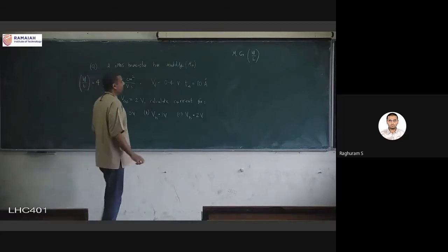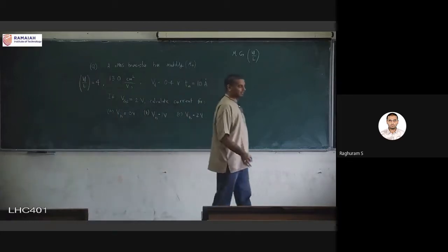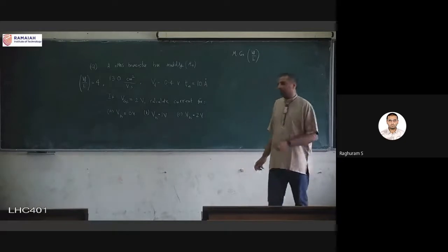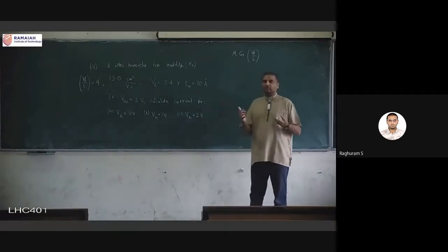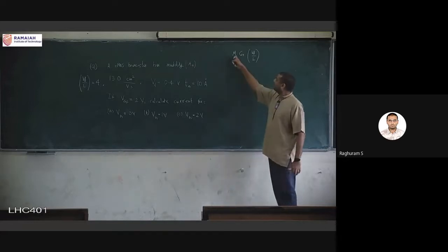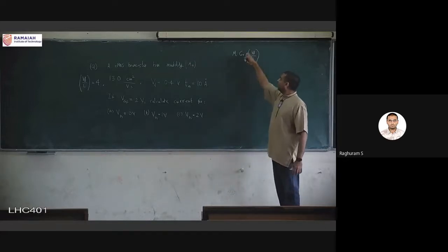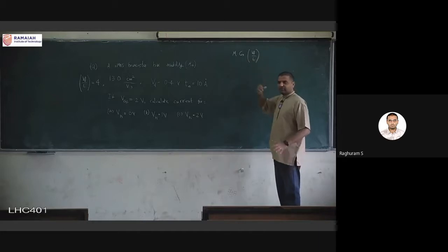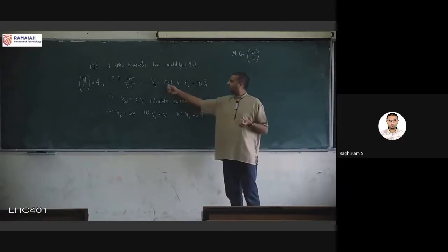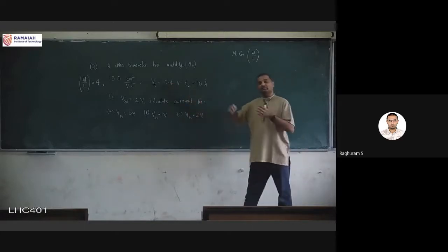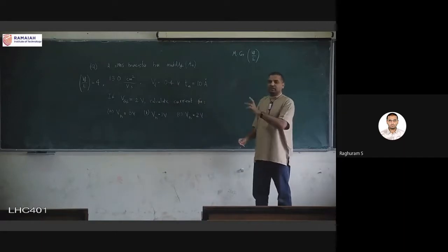The physical parameters, meaning the parameters that depend on the device and not on the terminal voltages, are mobility mu, C oxide and W by L. So for a transistor, after the fabrication, this is always fixed. The only things that can change are the electrical parameters.